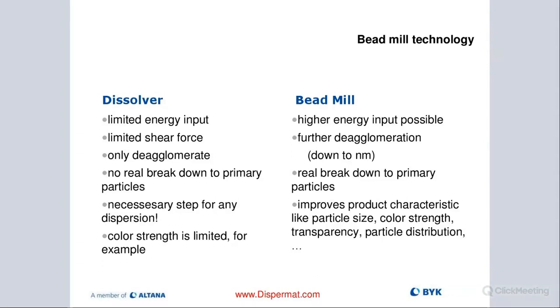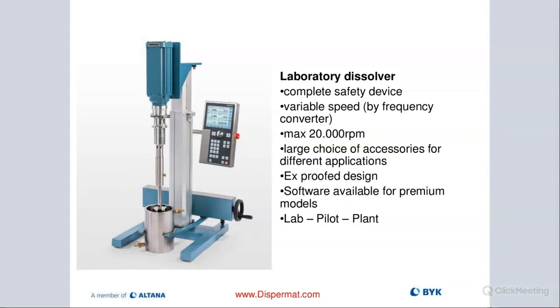With that, we can put in a lot more energy. It allows us to go down to the primary particle size, down to sub 100 nanometers, not unusual, especially for these new end-use markets. Even automotive coatings require really, really fine pigments, a small particle size, that makes these automotive coatings really pop and gives them a really strong and beautiful appearance, because they are milled really well. So that's critical to remember, the difference between the dispersing and what's actually happening when we are milling.